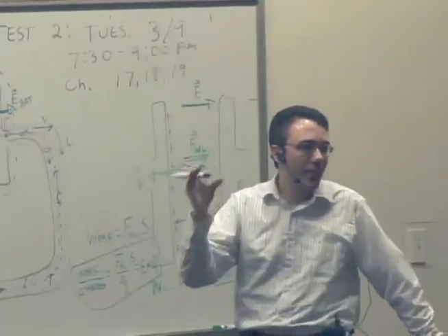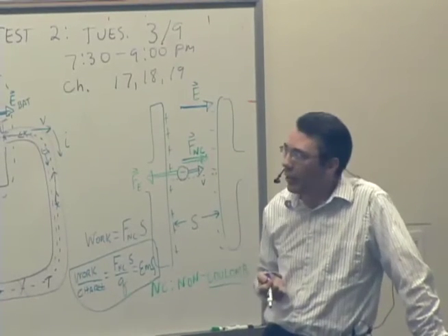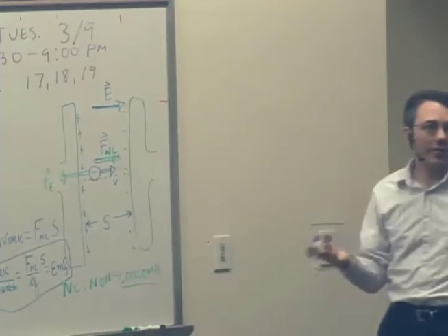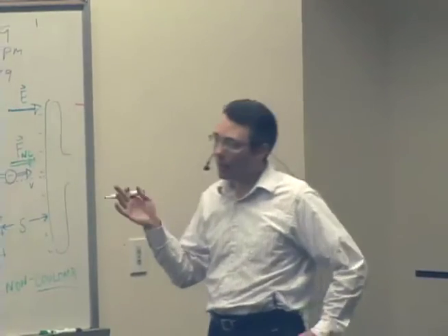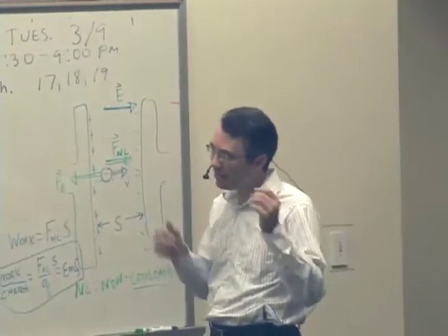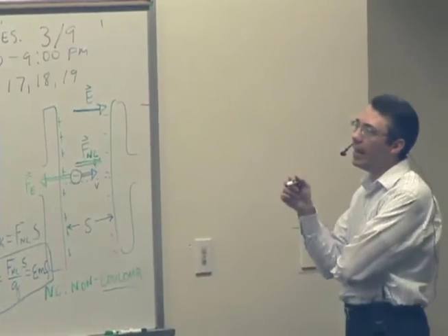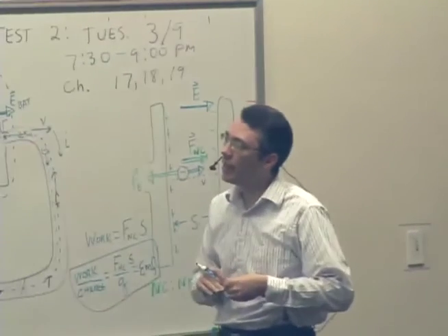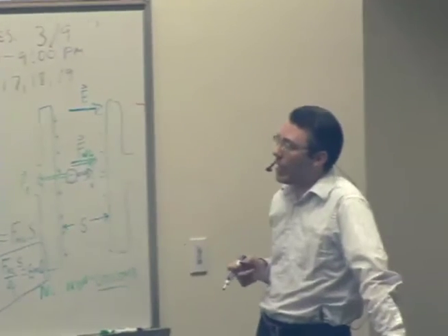Okay, so that means you can look at a battery, see what its voltage rating is. It's a 1.5 volt double A cell battery or a 9 volt battery. You can say, okay, that's the EMF, and that EMF is going to be mostly independent of what's connected to the circuit. If it's a non-ideal battery, you get into some issues, but in the case of an ideal battery, it's just a constant. It's just how much work the battery is going to do per unit charge, and it's independent of what's connected to the circuit.